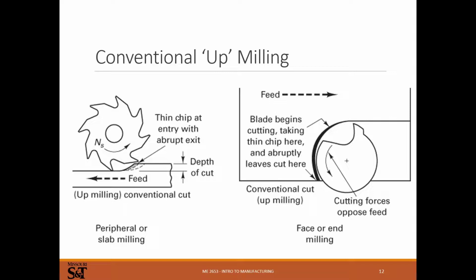So up milling is when, the tool stationary, we're moving our table this way, the cutter is spinning clockwise. We're not changing the direction of the cutter. The cutters can only spin clockwise. They can't spin backward. Bad things happen. I'm sure they do make some cutters, like a left-handed thread cutter, but I've not seen one. Some drill bits are like that, for removing bolts that have broken off, but it's very rare. So the tool always is going to spin clockwise here.